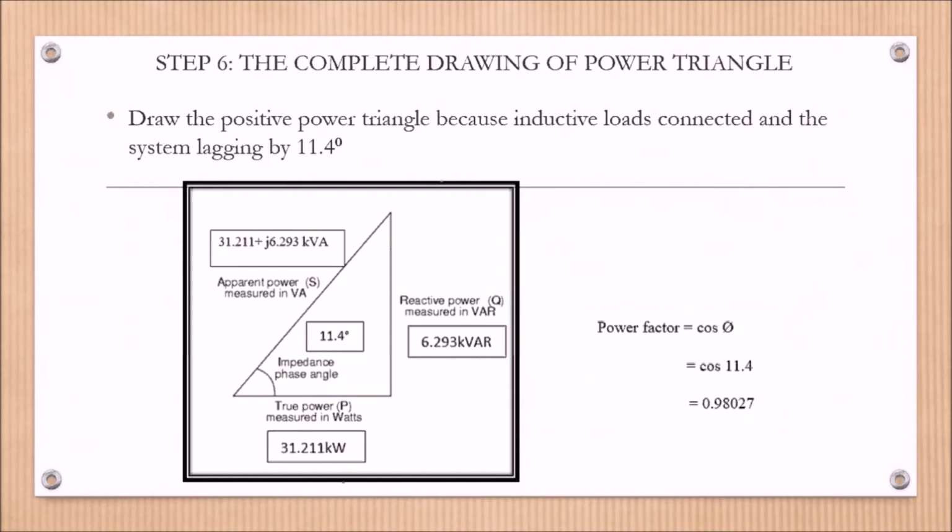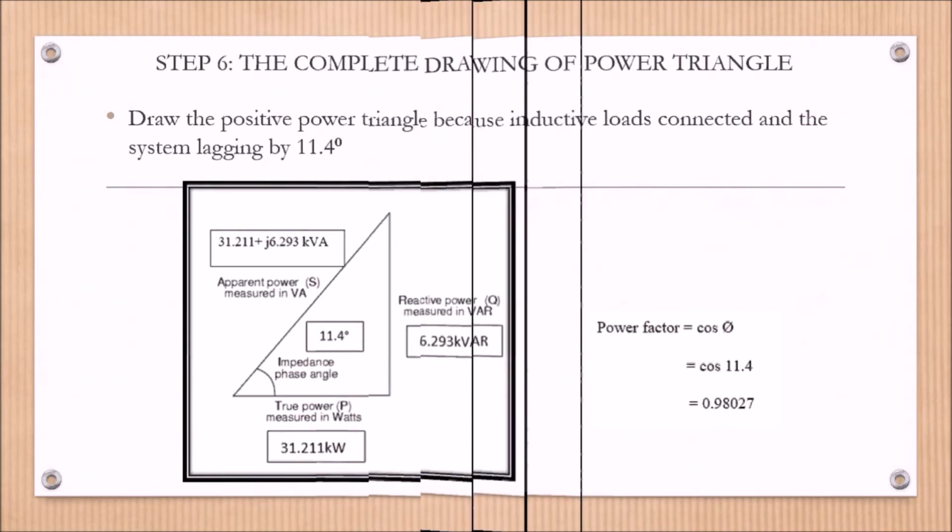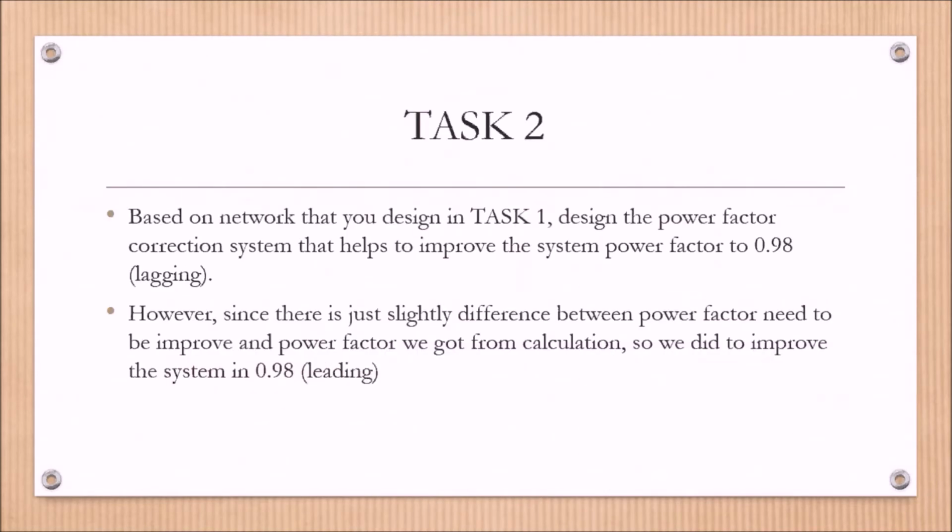We draw the positive power triangle because it is connected with inductive loads and the system is lagging by 11.4, and the power factor we got is 0.98027.